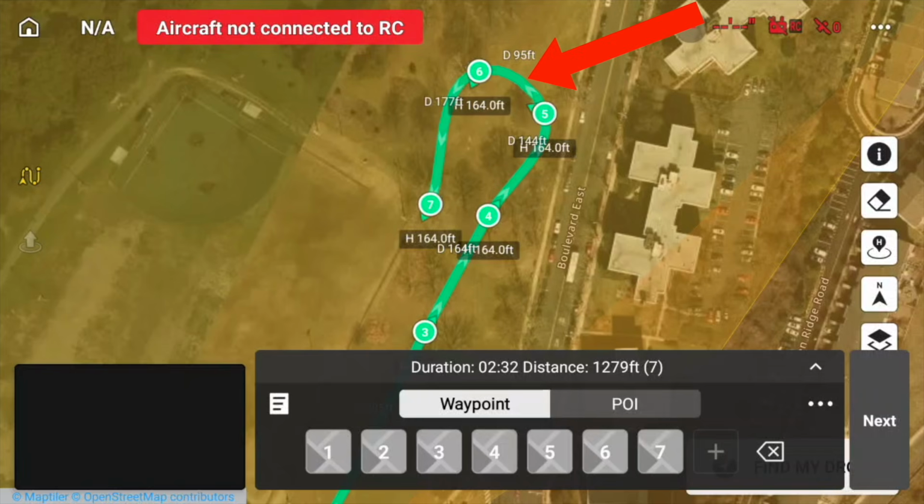The key to achieving the best results in a 2D mapping waypoint mission is to create small loops at each end of your flight path using 2 waypoints per loop. This technique allows the drone to make smooth, consistent turns between each flight line, reducing sharp movements and ensuring precise alignment and overlap across all image captures. By incorporating these loops, you'll produce cleaner, more accurate 2D maps with minimal stitching errors.